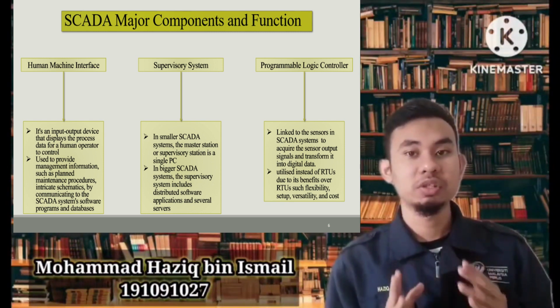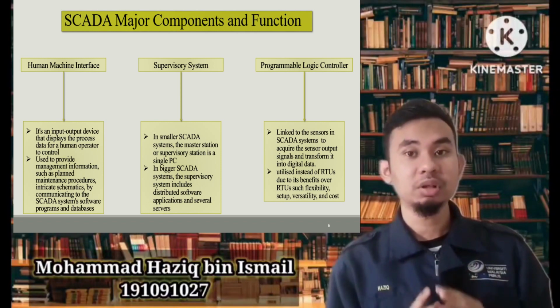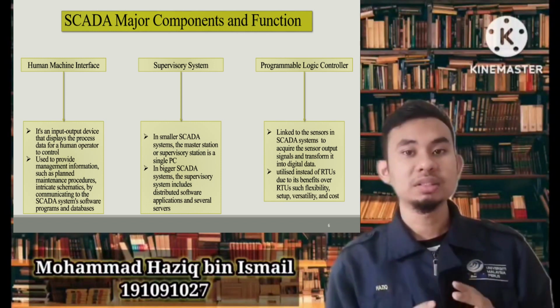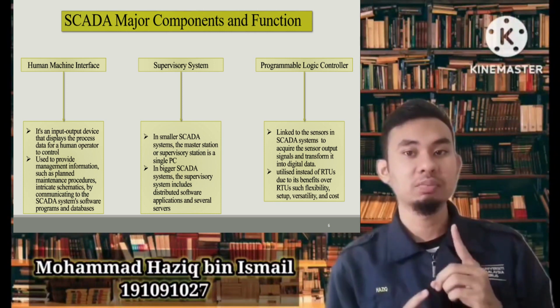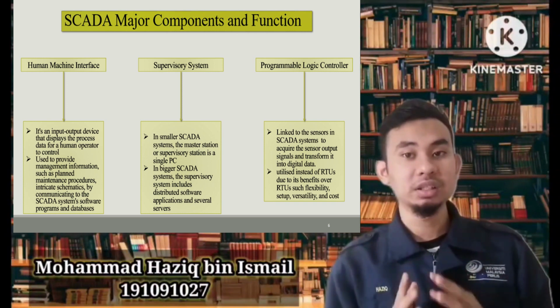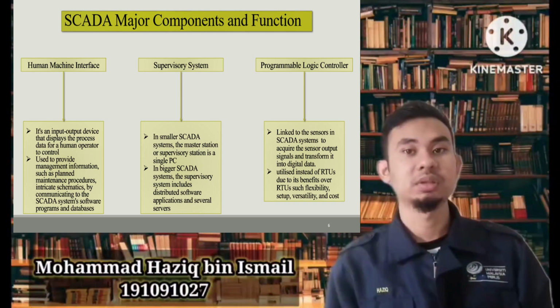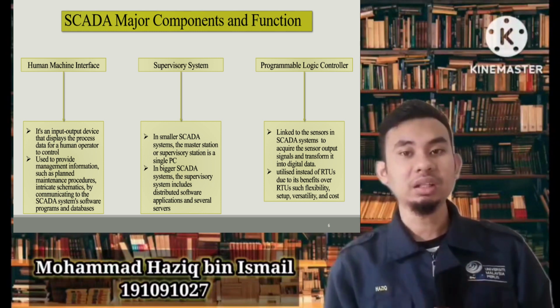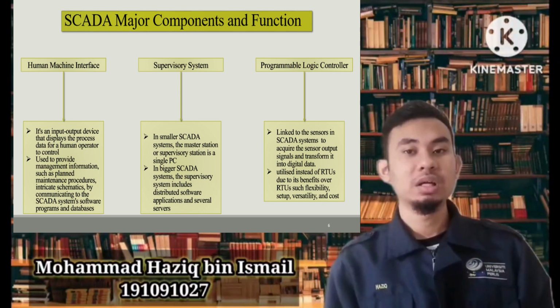Next is supervisory system. In smaller SCADA systems, the master station or supervisory station only requires a single PC, but in bigger SCADA systems, the supervisory system includes distributed software applications, disaster recovery locations, and also several servers. Then, programmable logic controllers, number 3.